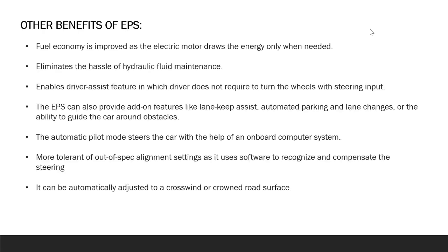There are also various other benefits of EPS, which is electric power steering. Fuel economy is improved as the electric motor draws energy only when needed. It eliminates the hassle of hydraulic fluid maintenance. It enables driver assist features in which the driver does not need to turn the wheels with steering input. The EPS can also provide add-on features like lane keep assist, automated parking and lane changes, or the ability to guide the car around obstacles.